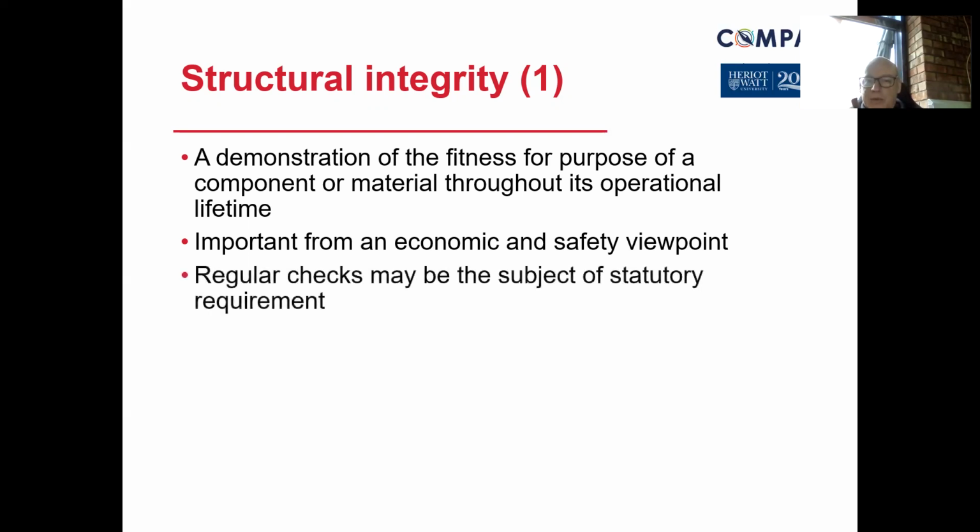Regular checks once you put something in place are necessary. So whether you class this as maintenance or servicing, for me, it's more monitoring and inspection. And historical information will tell us, as I said at the beginning, that certain materials and certain equipment will last for X amount of time, and therefore a preventative maintenance program, or programmed preventative maintenance, whichever way you look at it, states that those parts, those components, those materials need to be replaced at 6 months, 12 months, 2 years, however long it says in terms of its life cycle or expected life cycle.